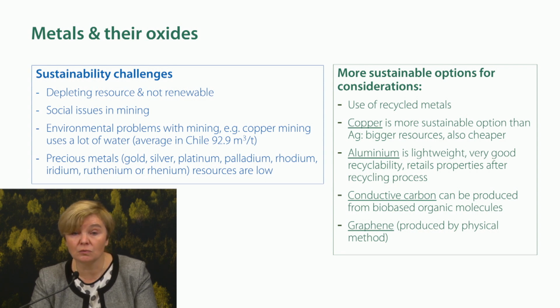Of course, you don't want to hinder the functional properties of the products, so you always have to evaluate the possibility to exchange your raw materials to others, depending on the product you have. Over-design is also costly, so instead of, for example, having silver, maybe copper is the better option. Copper resources in the world are larger than silver, so you could exchange it. Copper is also cheaper, so try to evaluate if you really need silver and rather choose other metals.